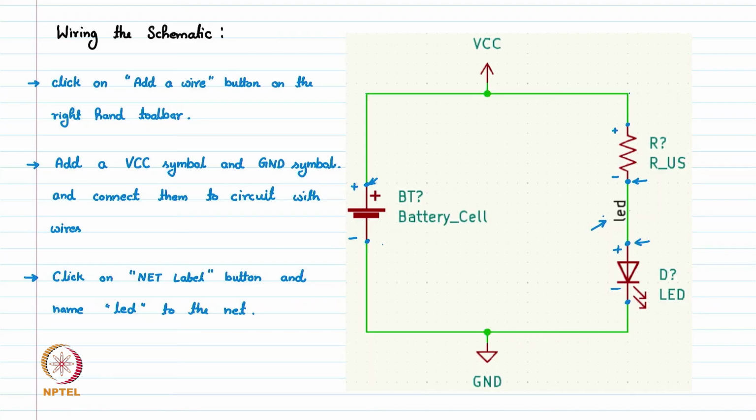So when we generate the schematic net list, all the nodes, all the wires we have in the schematic will be given some random name, NC001 or it may be a random number. The desired nets where I have put a net label will always be called whatever name we have given. So LED is the name of this wire. Anywhere, this terminal will be connected to the LED waveform.